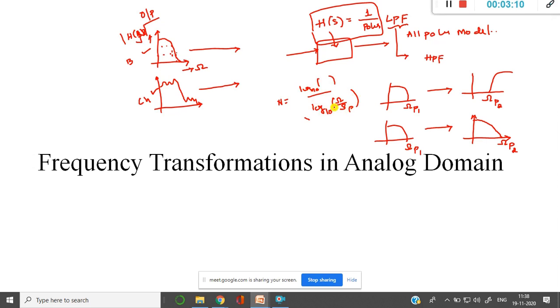Once again you need to do all this procedure and find out the value of n, then find out the poles, the sk values, then again go for h of s. So this becomes a very tedious job, only because there is a change in a small thing, that is the cutoff frequency. You need to start designing from the first, which is simply a very risky job, or too much time consuming, right? In the industry you don't have much time to initiate the system once again from the first. Many times this will be on a trial and error basis, because sometimes we choose this to be the cutoff frequency so that I will get all the frequency components that are required, and later on you feel that 2 radian per second is enough, and later you feel let me increase it by 1 more radian per second, and then you say let us design the filter for 3 radian per second. Now is it possible to start with the first? No, it takes a lot of time.